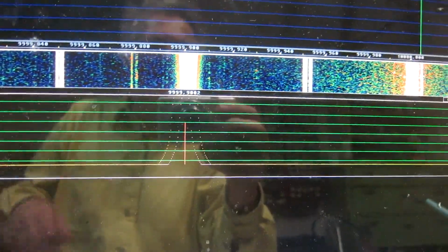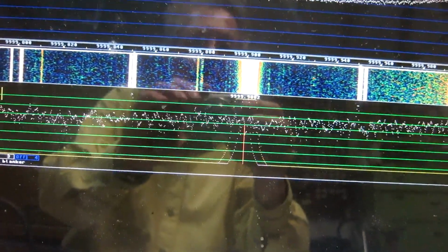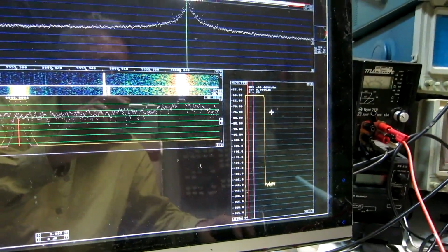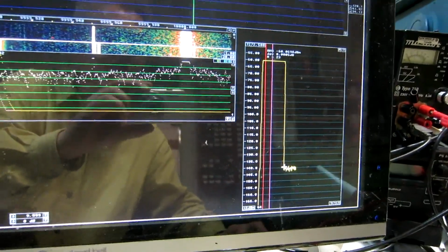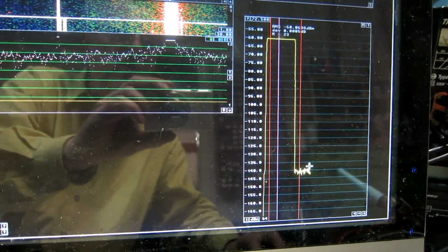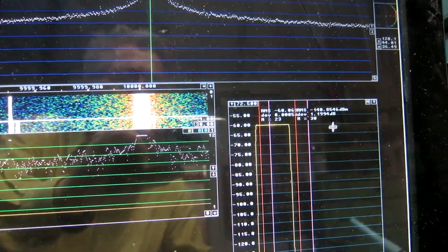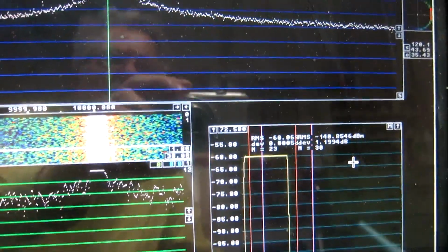And I switch off the extra generator to get the noise floor in 10 Hz bandwidth. At this narrow bandwidth, collecting data is slow. But now I have some points. Minus 140.9.